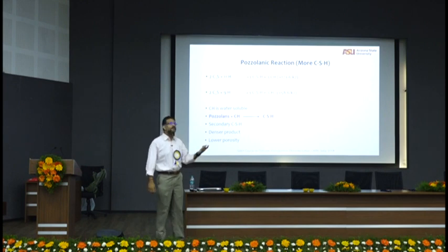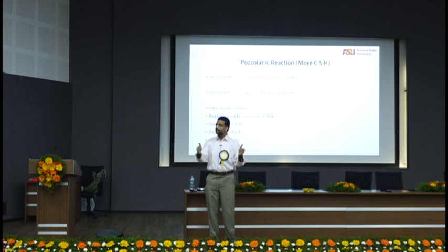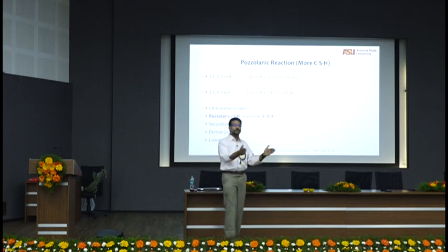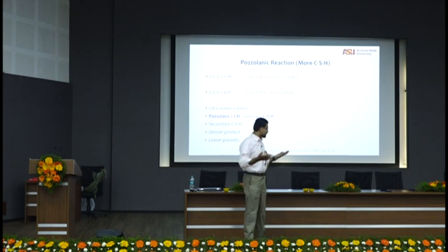So if you do performance specifications, check the fly ash. My total alkali content of my cementitious material should not be greater than so and so. How much fly ash will be acceptable for that? Now, I don't know, do you have alkali silica reaction in India? Do you have?